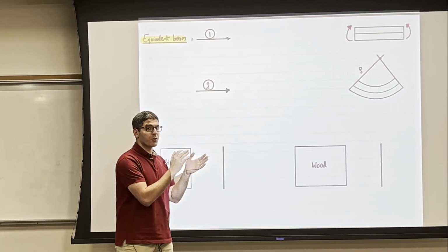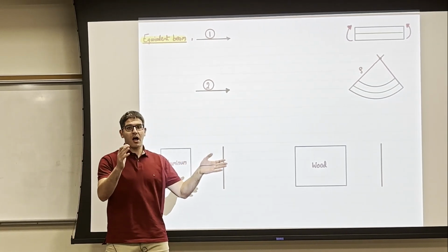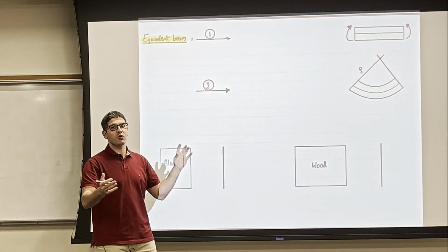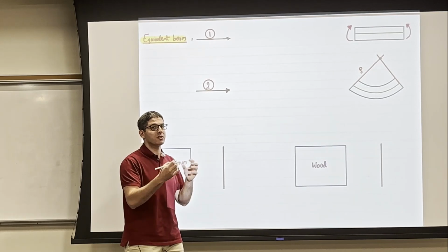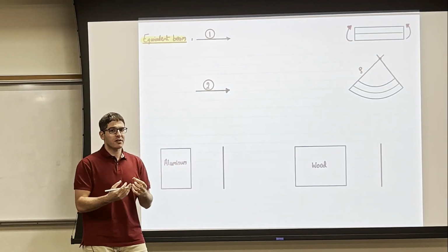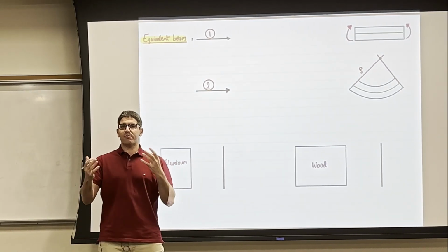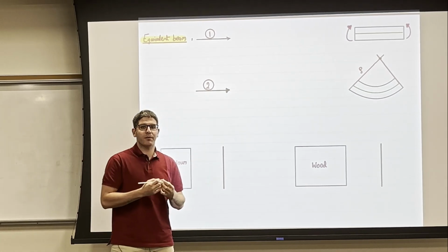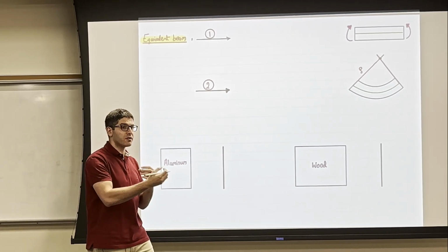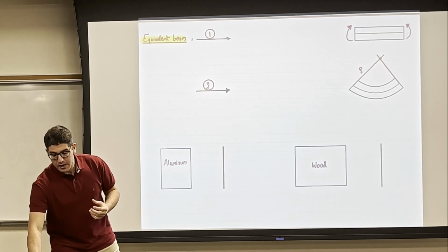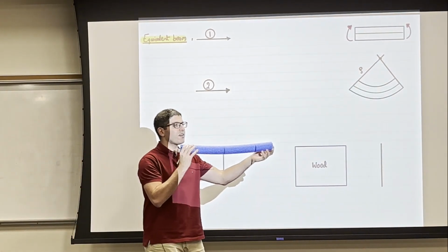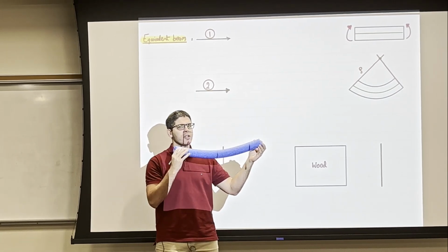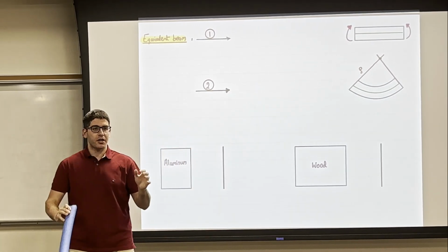Of course, if I build it with concrete, I will have very big column dimensions and beam dimensions compared with if I build it with steel, because steel is stiffer. But at the end of the day, if I build it with either material, I need to serve the function of people crossing the river safely. And by safe I mean the bridge shouldn't deflect much, whether it's made of steel, concrete or timber. And here's the idea.